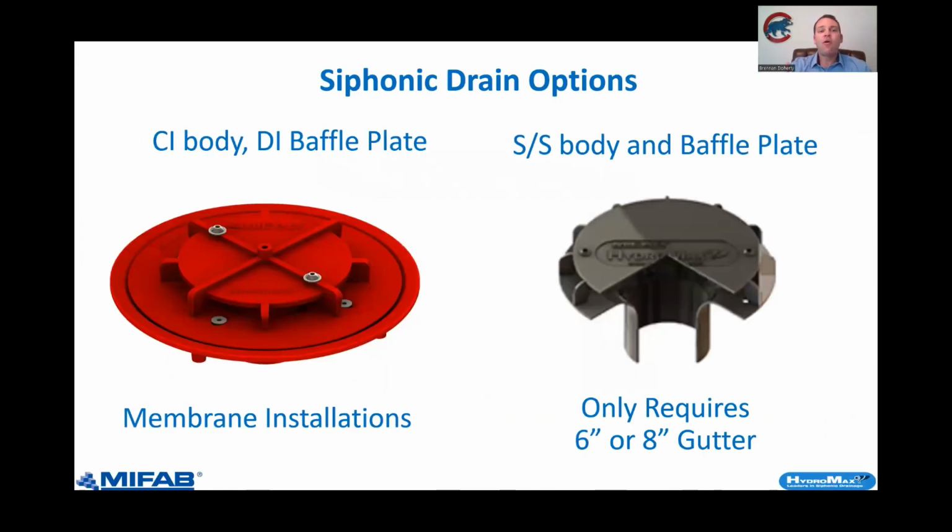First, really not a whole lot of drain options at its base. On the left, you got your typical TPO membrane. Membrane's going to go in there, clamp down with the friction force, same as we do with gravity. Here, we have a gutter style drain. We use this a lot of times on like stadiums or larger drains where it's maybe a one slope drain going to a gutter. What it allows them to do is keep everything flat, hug the corners, and get to your ideal discharge location.